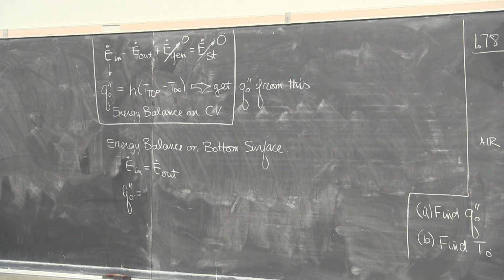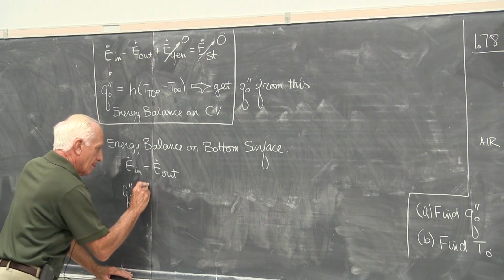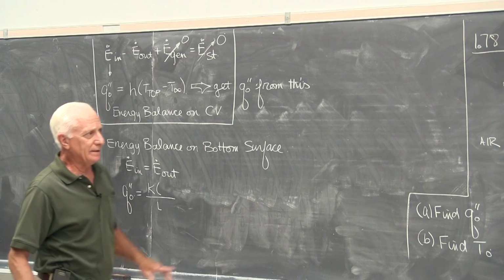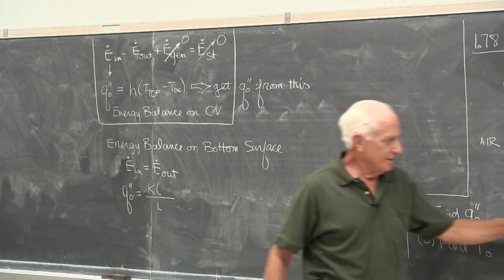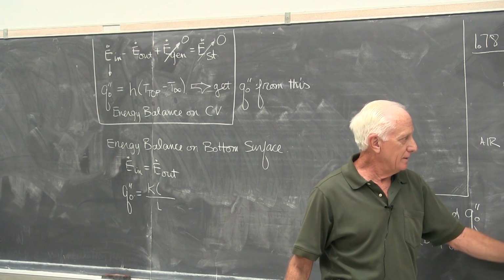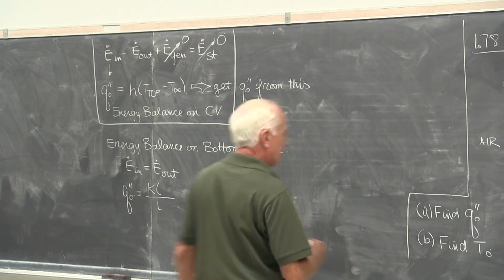And there's the equation, chapter 1 right there. Get rid of the A. K delta T over L. What is delta T? Hot minus cold. This is hot, the top is colder. Okay, heat's going this way. T naught minus T top.